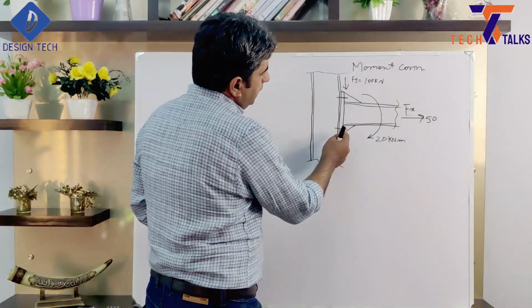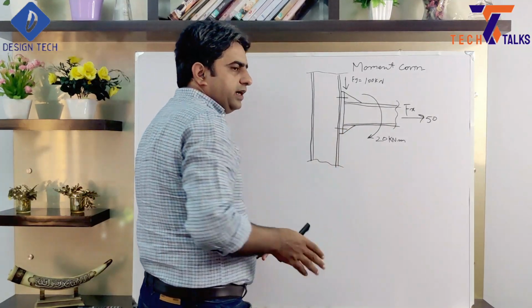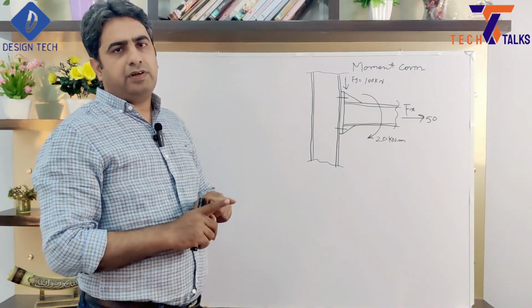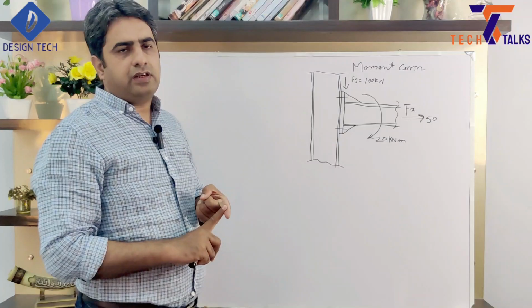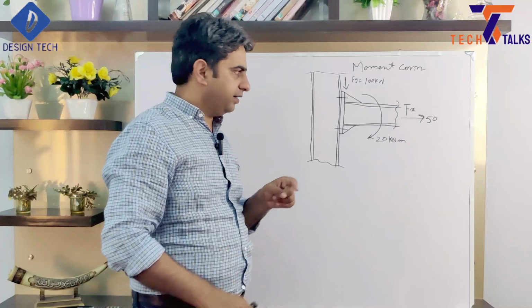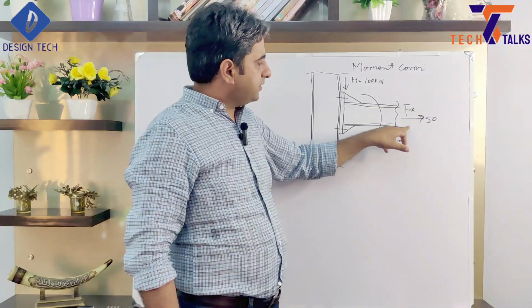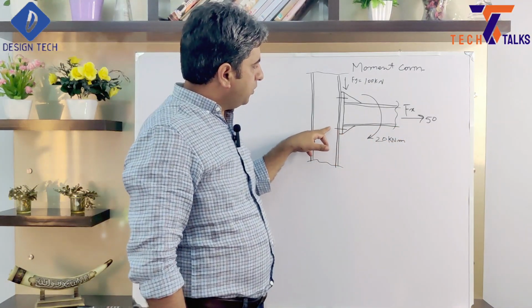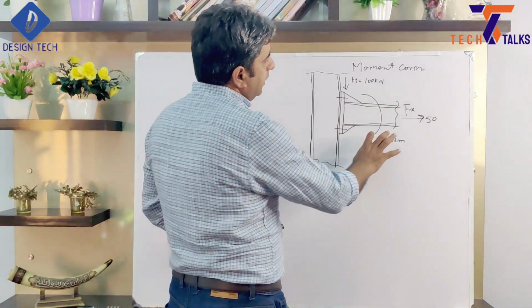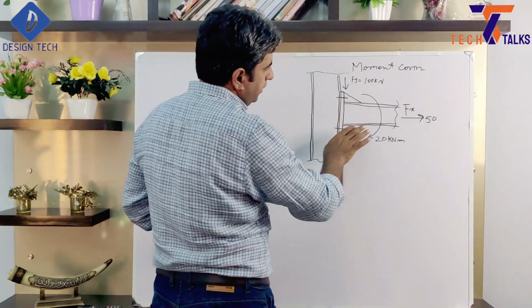When there is axial force, it will add tension force on these bolts, not shear like we considered in our pinned connection. Because in the pinned connection, either axial or vertical was giving a shear force, so that's why we took the resultant. But now Fy will give shear on these bolts, and Fx will create tension on these bolts, so we need to tackle both separately.